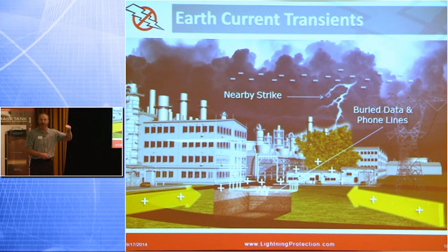And we see this on numerous occasions where you'll see a lightning flash, you'll hear the thunder, and automatically the DCS just starts shutting down. Nothing was damaged, but when they go back and check the report of why the DCS went through its shutdown scenario, because it thought that vessel had too much temperature in it and might blow up, it was a false signal on that analog circuit that created the trigger that shut down the system.